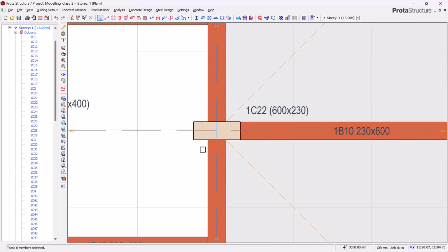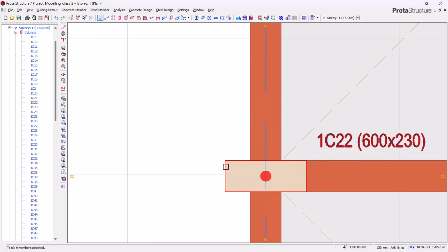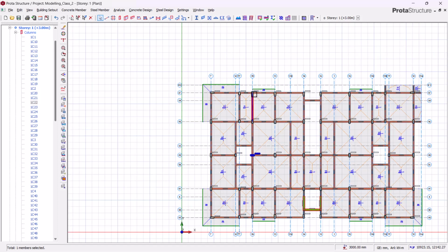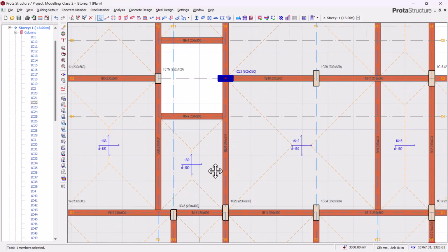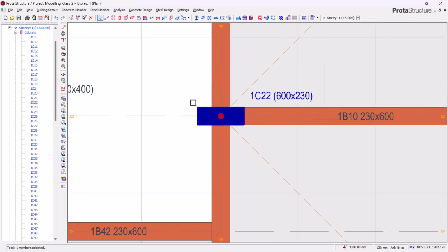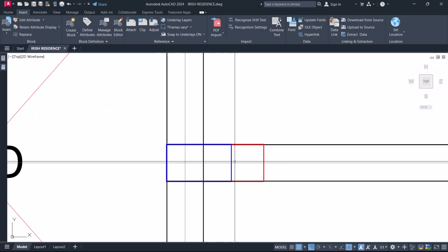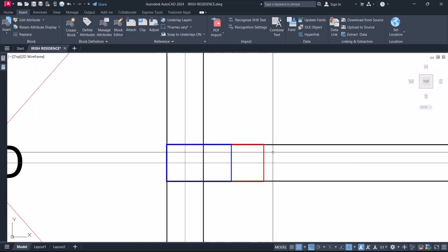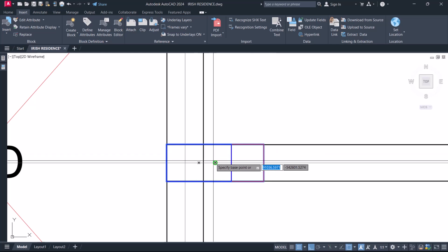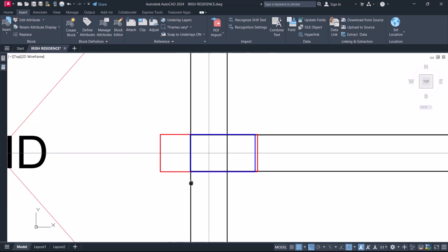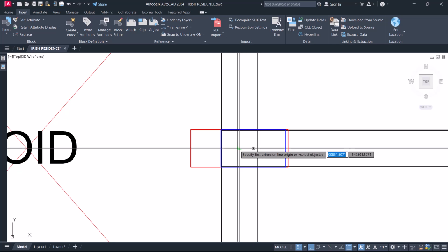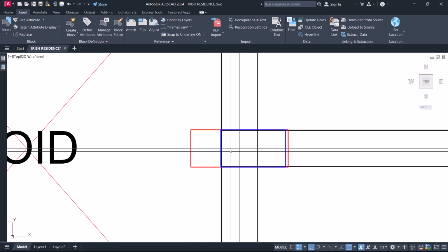Now the next thing we can do is we have to make sure that this column aligns with this point. All right, so we can at least get the straight edges with this builder's line when we align this first column to this last column. All right, so to do this, let's go back to our AutoCAD and come to this point. All right, so we'll be taking this column, which is the discontinuous column, to this point, and we have to dimension this.